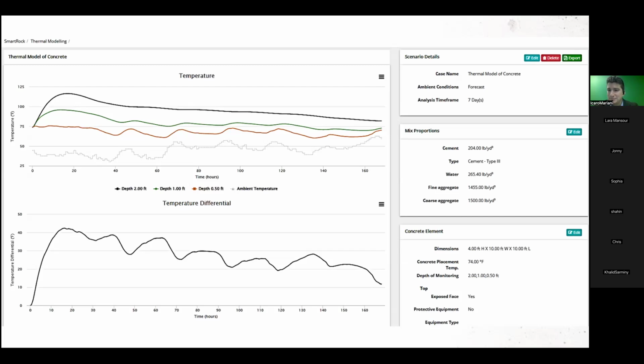That's really interesting. And I would say one of the reasons dams are actually measured more carefully is because of the safety factors included on them. All the structural engineering design, all the safety factors are based on probability of death. So you cannot go into a building and increase your probability of death compared to walking on the street. That is the deep foundation of every safety margin. And that's why dams have a much bigger safety margin, right?